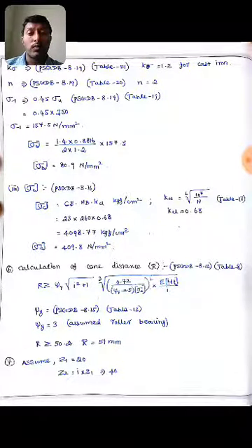Next, K sigma from the PSG data book page number 8.19 from the table 29. K sigma value is 1.2 for cast iron. n is equal to, PSG data book page number 8.19 table 20. So n is equal to 2. Sigma minus 1 is equal to 0.45 sigma u from the PSG data book page number 8.19 table 19. The sigma minus 1 value is 157.5 Newton per mm square.